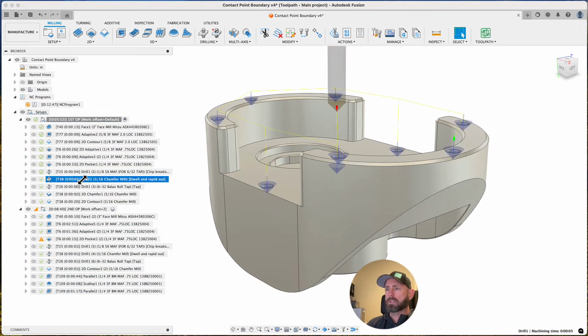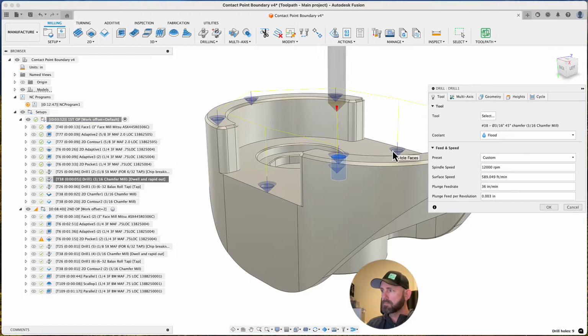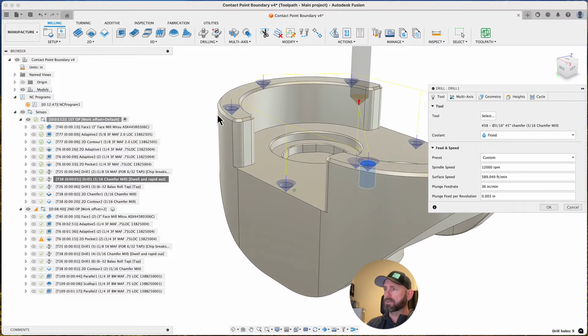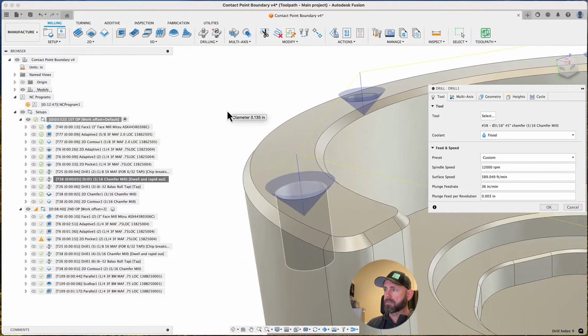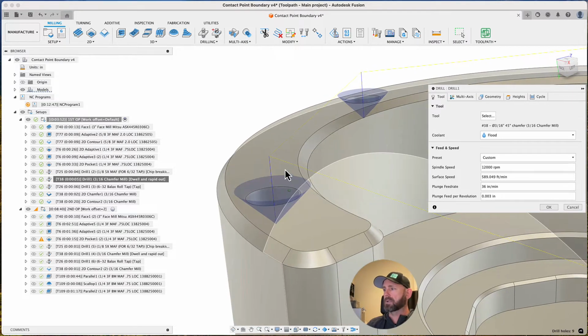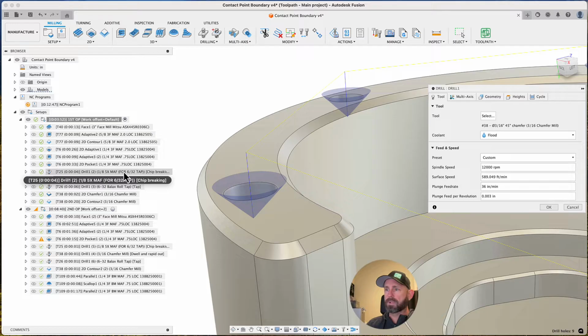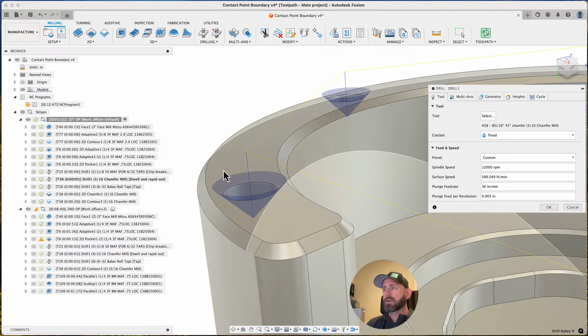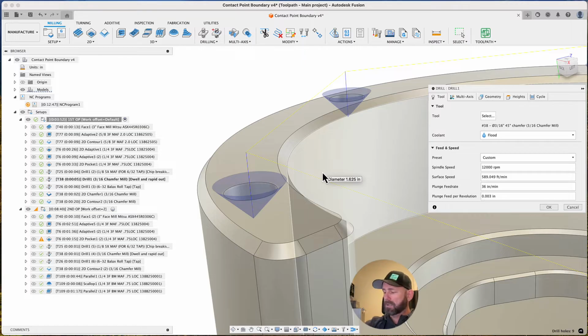All right, so then on the chamfer, I'm not using this chamfer tool as a spot drill. Some people might do that, but you're going to damage your drill. You're going to have inaccurate holes. You're going to have all kinds of problems. So this was a 140-degree, carbide, 3 flute drill. It's great. I don't need a spot drill for that. And if I did, I would make sure it was a bigger included angle than the drill that I'm using.